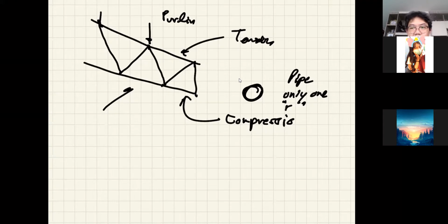So at least you go out and then someday someone brings the drawing of the factory to you. Hey, can you design a factory? You would say, yeah, sure. And most likely the factories will have the truss roof because the factory wants a large area underneath. So you can't have columns every 4 meters. The only choice they have for the roof would be the truss.